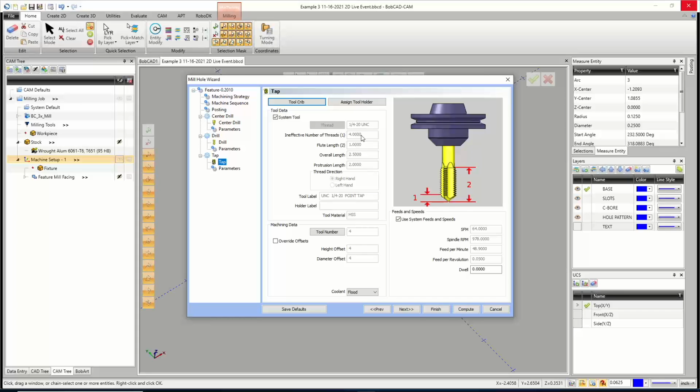I've seen it before where it has the drill going to a certain depth and the tap is either clear through where it's way deeper than it needs to go, or it's right at the level where it catches on the tip that the drill left in there. So, which might be a problem with one of the guys I know of. I'll talk to him.